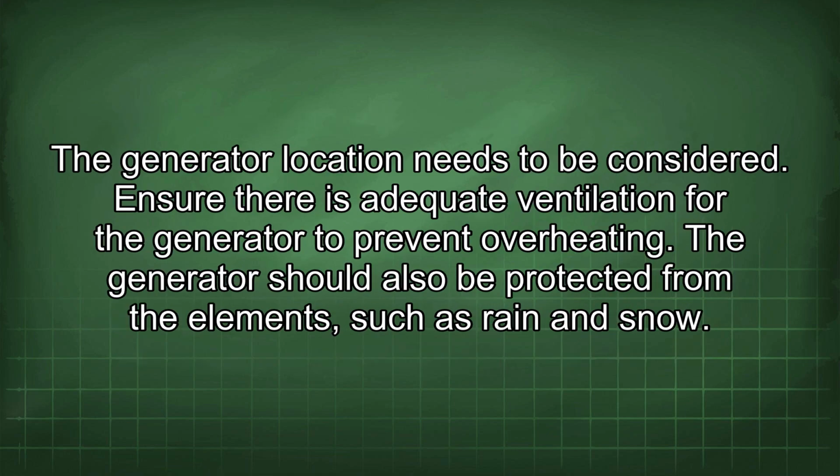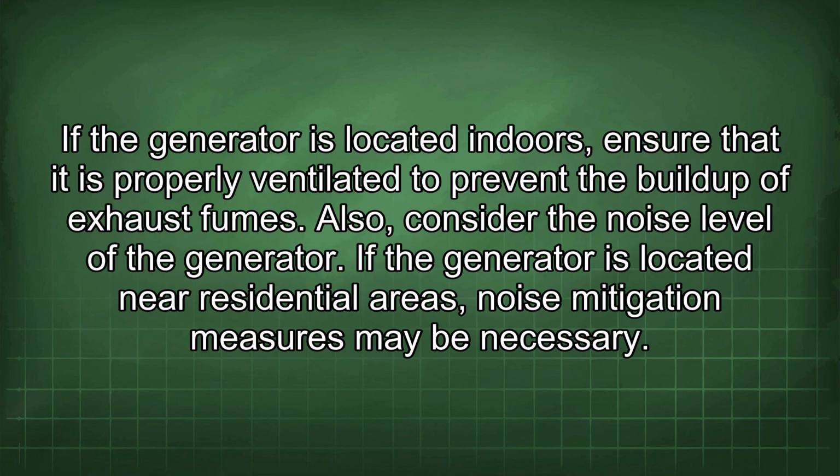The generator location needs to be considered. Ensure there is adequate ventilation for the generator to prevent overheating. The generator should also be protected from the elements such as rain and snow. If the generator is located indoors, ensure that it is properly ventilated to prevent the buildup of exhaust fumes. Also, consider the noise level of the generator. If the generator is located near residential areas, noise mitigation measures may be necessary.